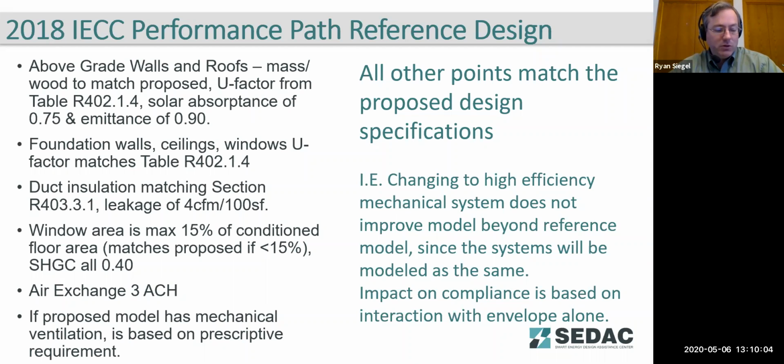And that's very useful to go through as an initial check rather than turning it over to the building plan inspector and have them find something missing. So best practice would definitely be have both the design professional complete the checklist first, and then go ahead and submit that with the plans, and then the plan reviewer can also do a verification on it. It makes it much quicker and easier to do.